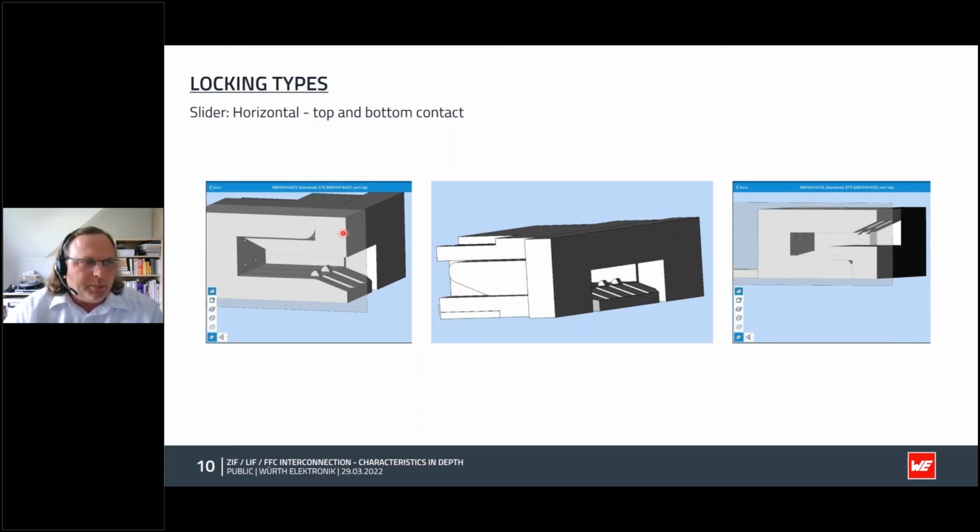The slider is valved. You can see it here. This enables us to route the cable at right angles when pressing it and at the same time make contact on the pronounced part of the slider here. The cable is thus pressed more and more strongly against the contact teeth when locking.